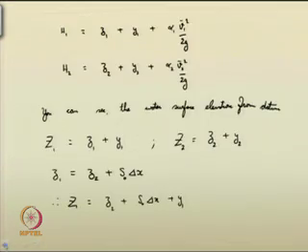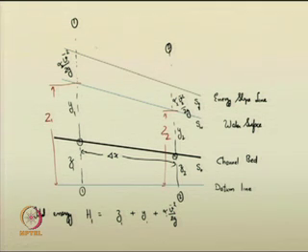So, as you see here in this figure, your energy line, your energy is getting decreased. Whatever total energy was there at section 1, H1, it is getting reduced to H2 at section 2. So, what is the energy loss? What could be your energy loss? H1 minus H2 will give you the energy loss, right?